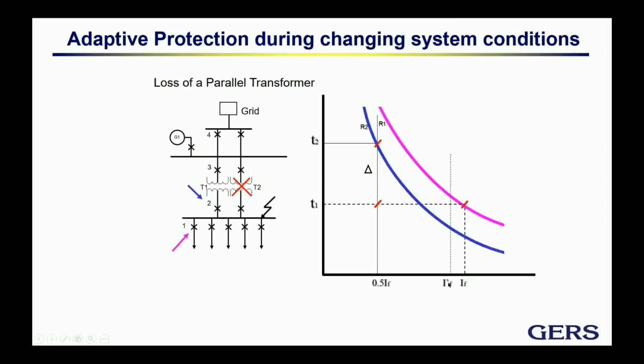In this case, if we were going to have the operation of relay number 1, you will see here, of course, that it will be T prime 1. And relay number 2 will be this one here, T prime 2. And in this case, T prime 2 is a lot faster than relay 1, meaning that relay 2 will overlap relay 1, which we cannot accept. No way.